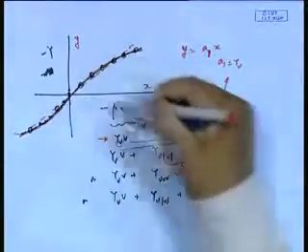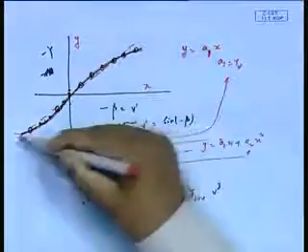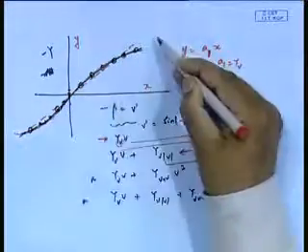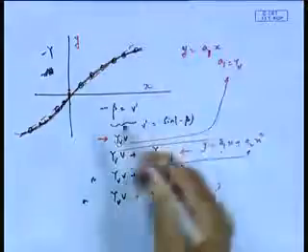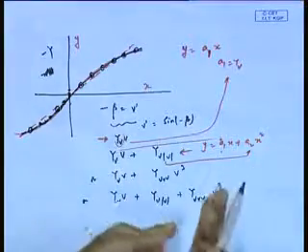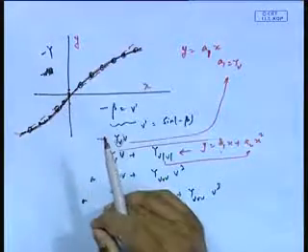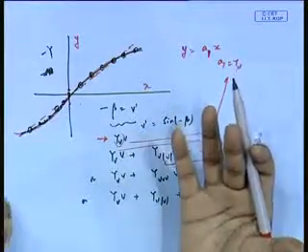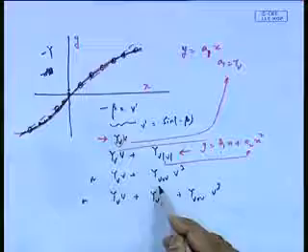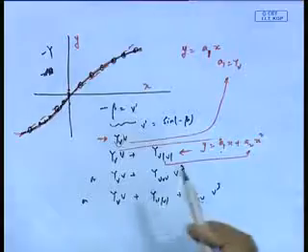If I want to now fit this one, what I am trying to say is that you have actually got y versus v. Now, it is not a straight line. Suppose it is a straight line also, then depending on the model you choose, you take that curve and fit that curve, least square curve, simple as that. That is why I wanted to have this nonlinear thing, because remember they are coupled. When you do the experiment, there is nothing like linear and nonlinear. Experiment is not bothered what model you took, experiment simply gave you what is y force against v. It is up to you to model.